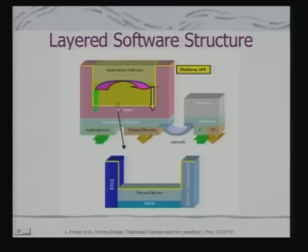In fact, TI's OMAP provides Linux based APIs, and this software layer of the platform would consist of device drivers, that is abstraction over the IOs, and an RTOS, that is abstraction over the concurrency model, the model to support threads, processes, etc. And if you are actually looking at a distributed system, it should also have the network communication support.